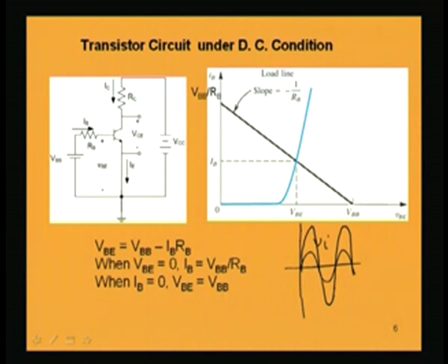Of course, this will not be exactly in the same phase, as we will find later; it will have an opposite phase. That means the output voltage in a common emitter transistor will be out of phase with the input. How is this signal coming out of phase? One hint we have just now is that it is negative with respect to the collector current, and the collector current is in phase with the base current.